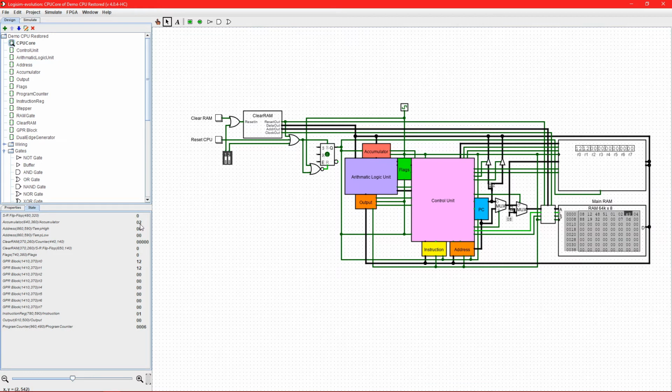And just like that, the accumulator has a value of 2. Now it's going to shift whatever's in register 1 over 2 bits to the right. So now the output register, which is here, has basically 18 divided by 4. So that's 18 shifted to the right 2 places. And it looks like it's going to be set back into the accumulator. Yep. And the next instruction will be an add instruction.